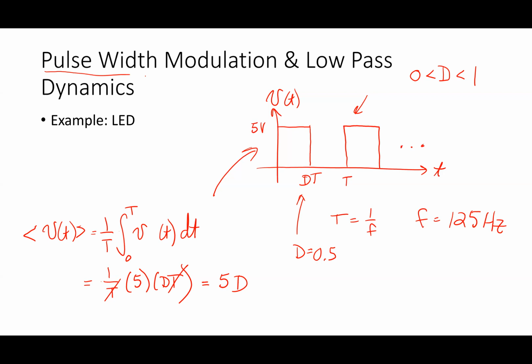But to make it work, it's all predicated on this notion of having a system that has what I call low pass dynamics. Like in the case of the LED, it's your eyes. Right? I can flash the LEDs fast enough that you don't see it. And the nice thing about that is it allows me to create a variable voltage source on that LED, right? That would be much better than creating a potentiometer to control that voltage.